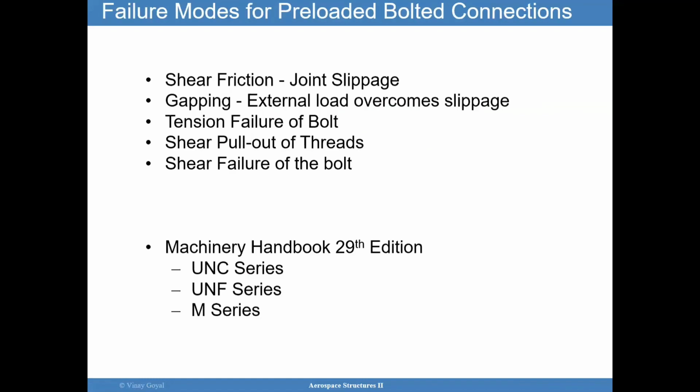So the failure modes in general will be shear friction, gapping, tension failure of the bolt, shear pull-out of the threads, and shear failure of the bolt. That's for the bolt specifically, but you also want to consider the membrane behavior.